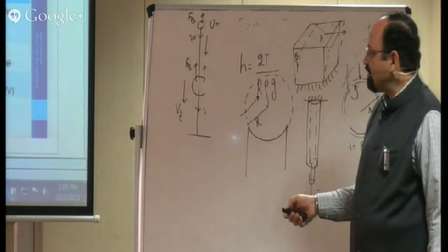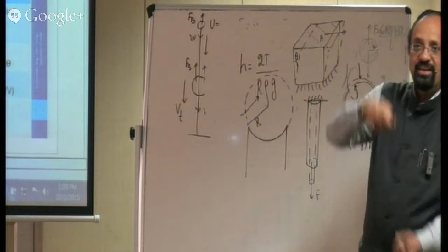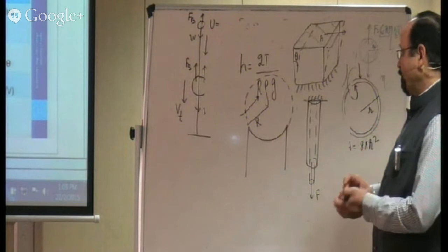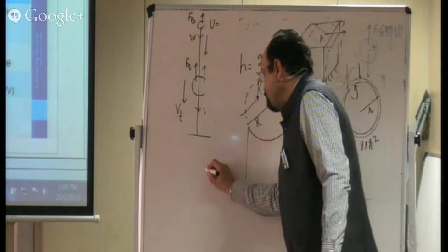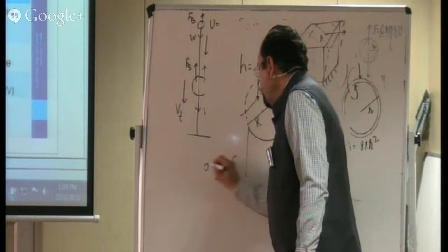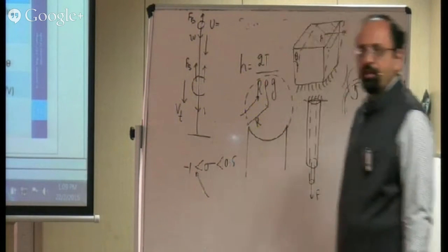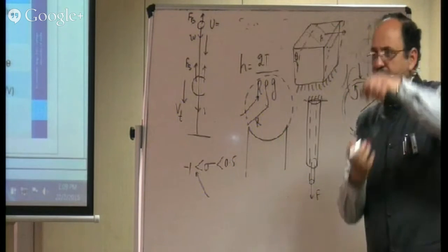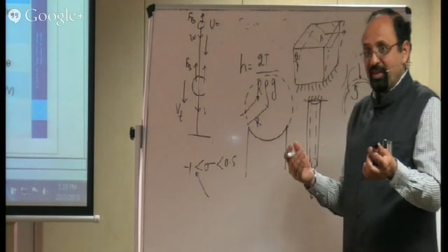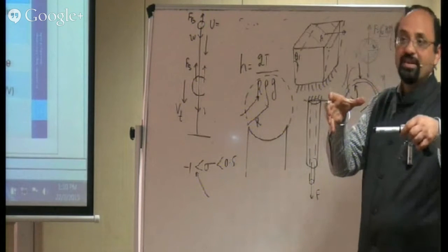And again, you see what I have here, negative sign. Normally we see that when there is an increase in the length, there is a decrease in the radius. But let me tell you, this Poisson's ratio theoretically lies between 0.5 and -1. When it is -1, what does it mean? It means if I am increasing the length, its radius also is increasing. Certain materials are like this, right? Certain organic materials are such that when you try to increase the length, their size will increase.